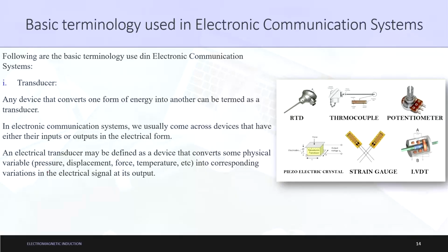So, it can be pressure, displacement, force, or temperature. What it does is change this physical variable into corresponding variations in the electrical signal as its output. The output is nothing but an electrical signal here.